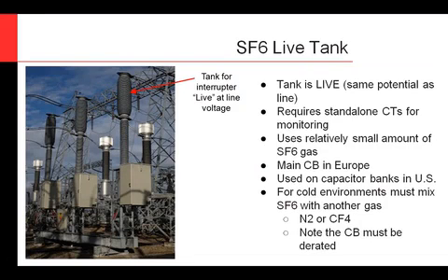Moving over to the SF6 live tank circuit breakers. Once again, live tank means that the tank is live at line voltage during service. So these are very popular. You'll only see this, or in Europe you'll only see this style of circuit breaker. In the U.S. you'll see some of these here and there. As I said, the main is dead tank circuit breakers.